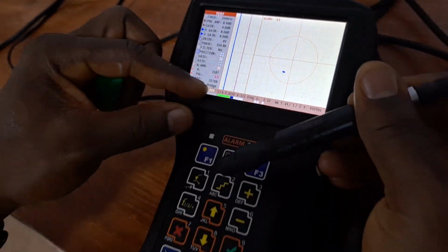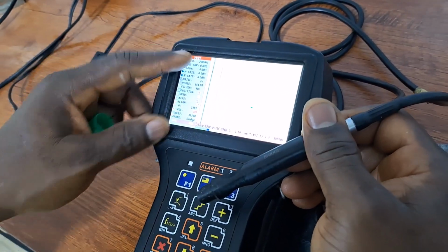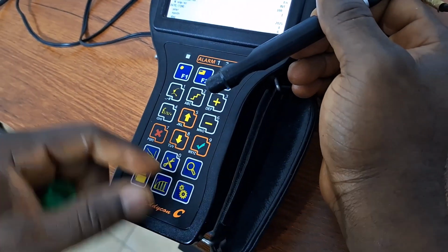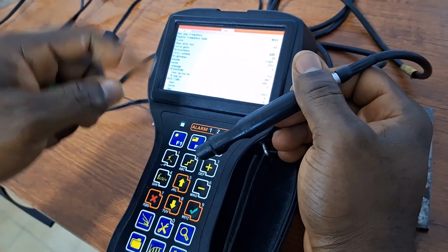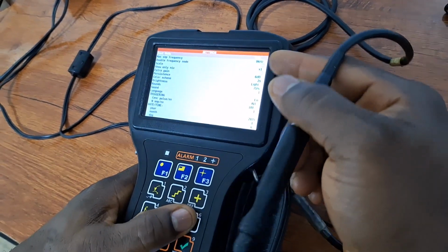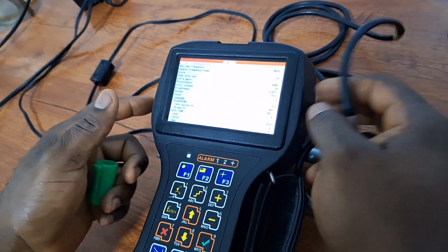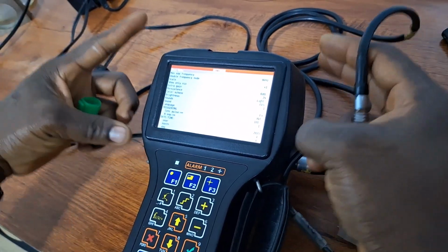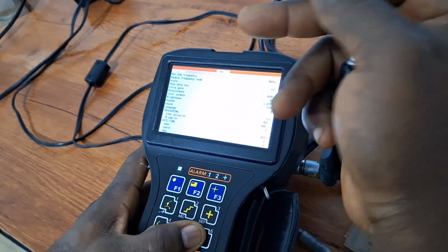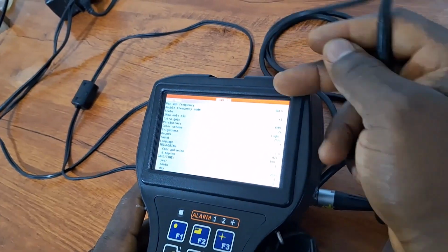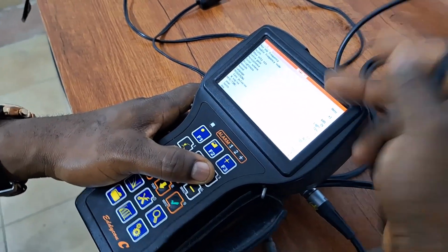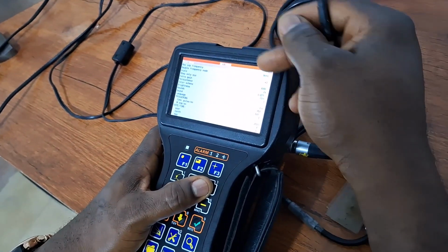So that covers generally the entire screen. Then you can see additional settings when you press settings here. Here you have your expert mode, your conductivity mode, and your test mode. The test mode is used when the equipment is being calibrated by the manufacturer or an accredited calibration company for annual calibration, or when you want to do repair. So you don't need the test mode as an inspector. The expert mode is what you use for weld inspection, bolt hole, or any other form of surface inspection.